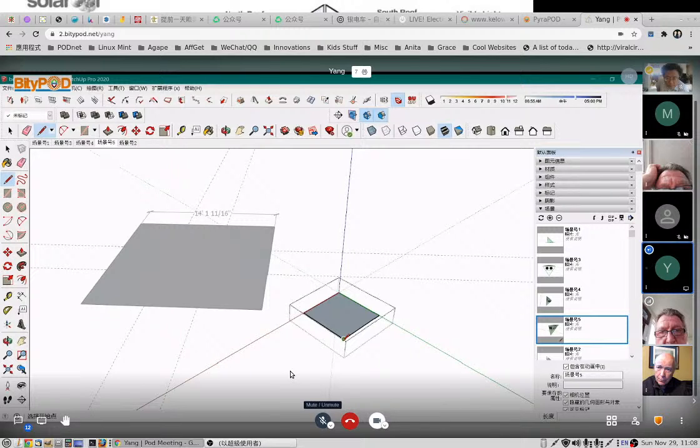So what we're going to do now is the arches, okay? The arches are 14.14. We want to get the radius of the arc, and the origin is on the axis that we're looking at. We're going to put the point of origin of the arc at the distance from the corner along the axis, which is 14.14 feet.